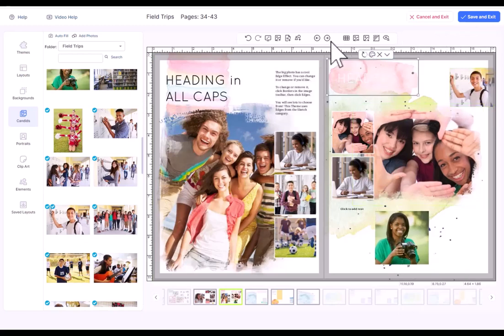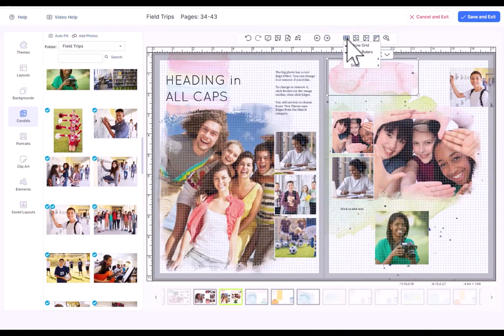Next up, I'll show you up here is a grid. And so if we turn on this grid feature, I can show the grid. I can show the rulers, which are here. And then I can show the granularity of the grid, 1/8 to 1/2 an inch, and then snap to the grid. Okay, so when the grid's on, I can come in and do things like this.